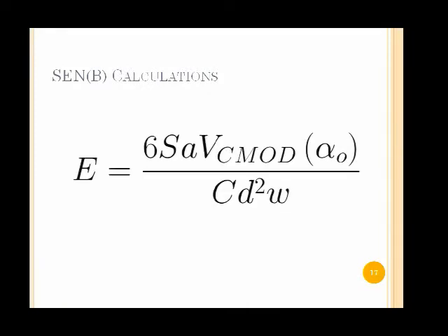So the idea that we're going to use is that during that loading and unloading, the elastic modulus, which is here, doesn't change. So we have a general equation just for elastic modulus. This is the span of the beam, so that's constant. This is the initial length of the notch. This is a geometric correction factor for the beam, and that alpha is the ratio of the initial notch to the full fracture ligament. And this is compliance, depth, and width.